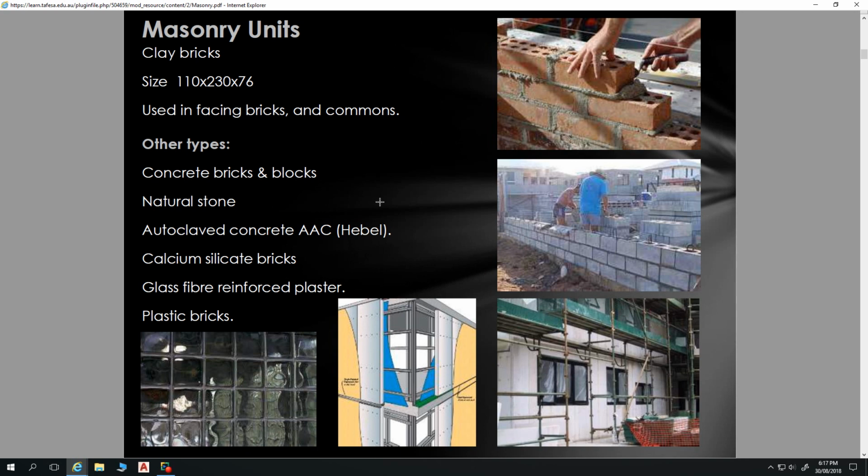I've specified it twice. Once it was as a packing material in a retaining wall. So a retaining wall that had earth in behind it had to use very large universal beams, much larger than the width of the sleepers. So there needed to be some sort of packing material in behind the concrete sleepers. And so that recycled plastic bag timber works really well in that scenario.